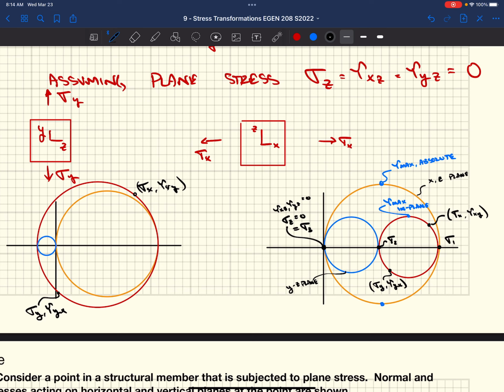And we draw a Mohr's circle, and that Mohr's circle now extends on the other side of our vertical axis, right? Well, that third point, sigma 3, in plane stress is always going to be sitting at the origin. It's zeros. You know this point. And so when we start drawing circles between sigma 1 and sigma 3 and sigma 2 and sigma 3, these circles are going to be smaller than our in-plane circle.